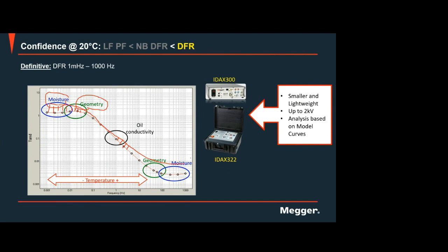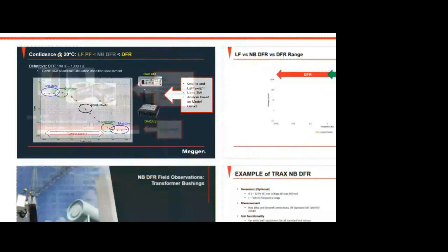And also on this higher frequency region, you can confirm if you really have the problem with the geometry and the moisture here. Okay, and that's the full DFR method. So with the full DFR method, it will give you a conclusive insulation condition assessment.